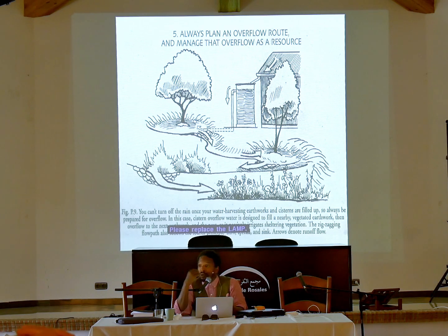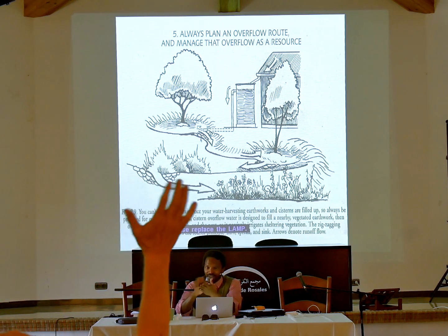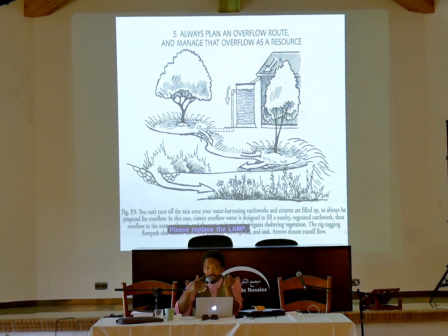Yeah, right, erosion. So the stone is able to withstand the movement of the water, the shearing. It's much better suited to withstand the shearing caused by the water in the soil. Because if you don't use it, and you've seen it in places on the camp where there hasn't been any use of stone or plans made to manage the flow of water, you start to get scouring. The water will begin to erode some of the soil. So the use of stone on the spillways is a way of preventing that from happening.